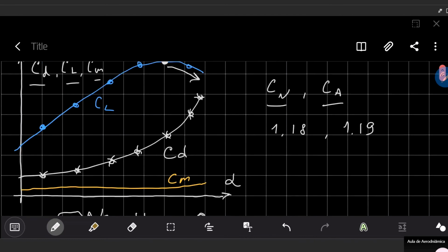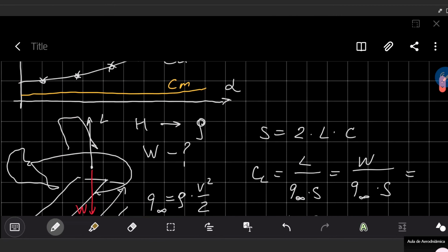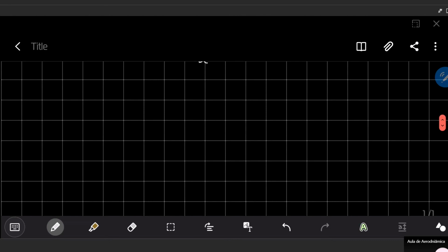and also in the part of conversion between aerodynamic coefficients. I would like to answer the question of Giovanni about lift to drag ratio. Lift to drag ratio is the aerodynamic criterion of perfectness of the aerodynamic body. So we take the lift force, which is created by the airplane or airfoil, and divide by the drag force created by the same airfoil. Dividing these two forces, we see how performant our airfoil or aerodynamic body is.